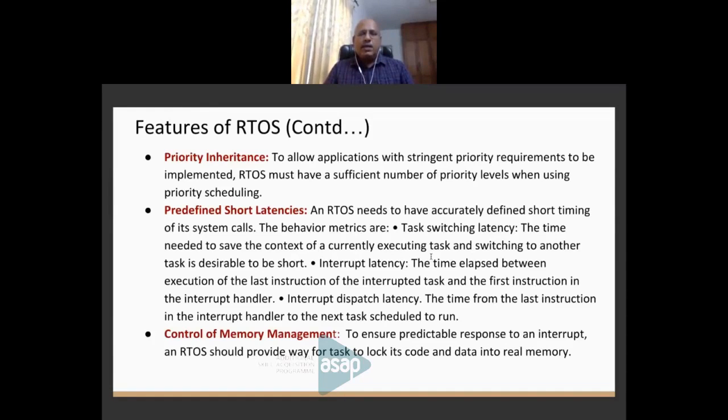which is typically in the order of microseconds, 10 microseconds and things like that in many RTOSes. Compared to an interrupt latency, which is talked about at a microprocessor level and is maybe a microsecond or so, a task latency, since it comes under the umbrella of the operating system, has a lot of overheads in operating systems. So that will be many times an interrupt latency. That is what we need to understand. So we'll go to the next one.